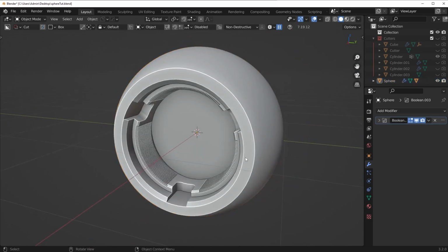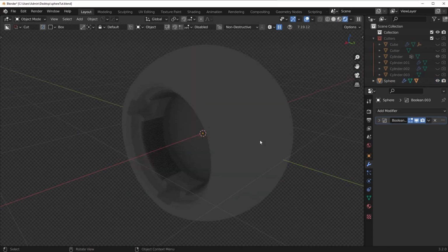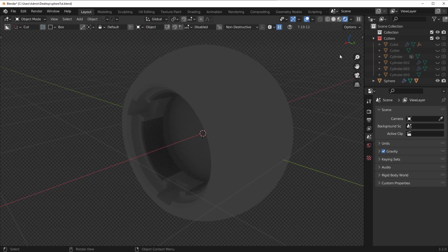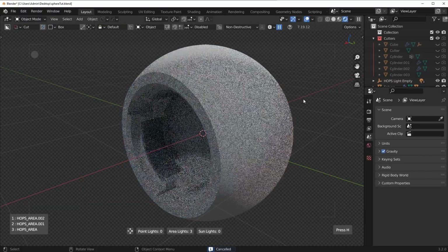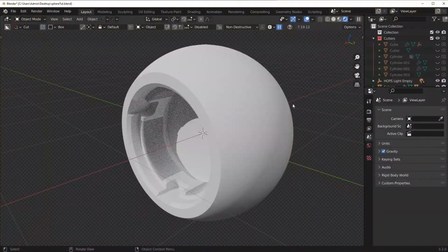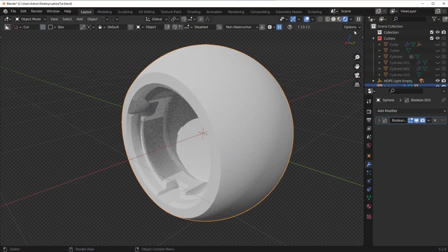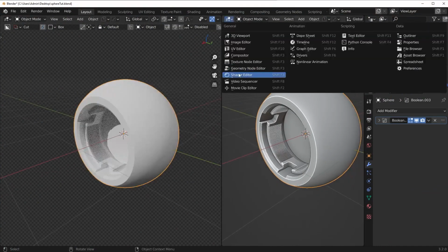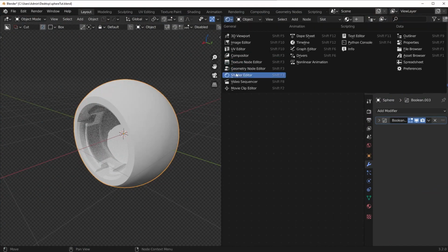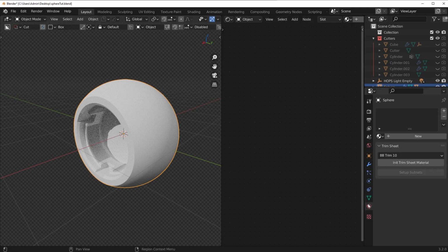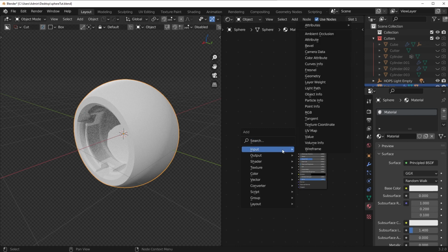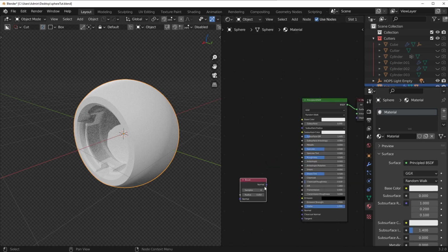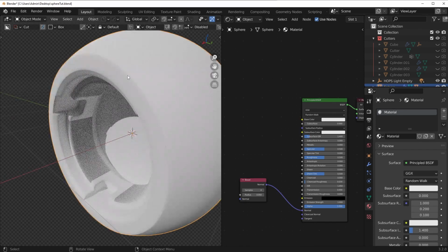Whenever you're rendering, if you want to have a preview of a bevel, check this out. If you go into rendered mode, and with hard ops, you could just press Q and add in some lights, press the W key. But basically what I could do instead of adding in a real bevel is go here to the shader editor, and we need to add a material first, like that. What I could do is add in a bevel shader. So Shift A, input, add a bevel, and then connect this up to the normal slot. And you're going to see we have a nice little bevel around there.